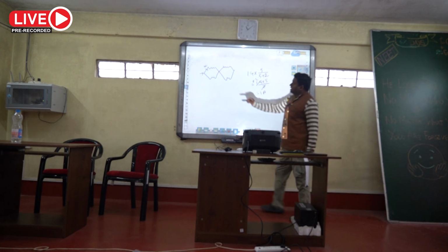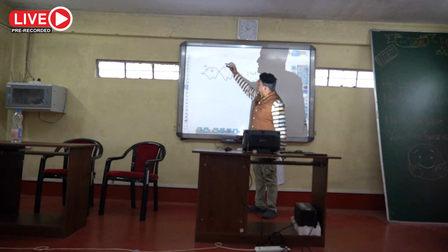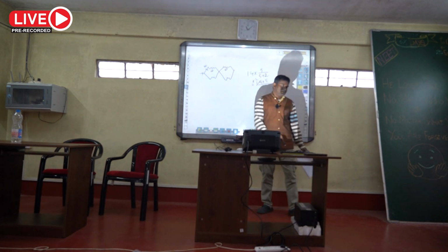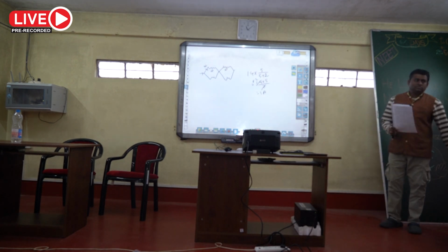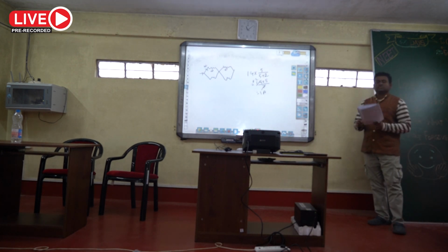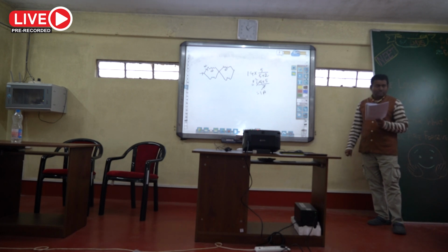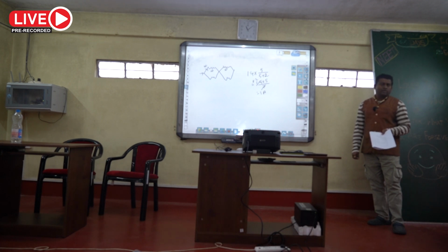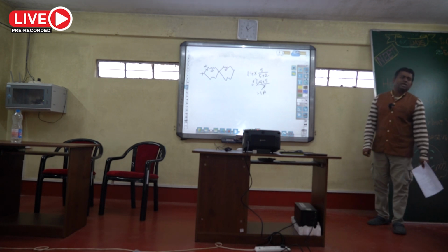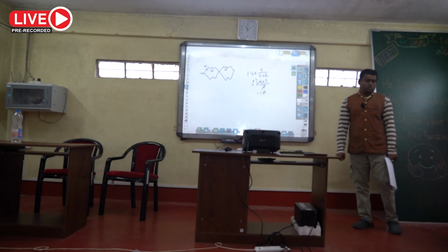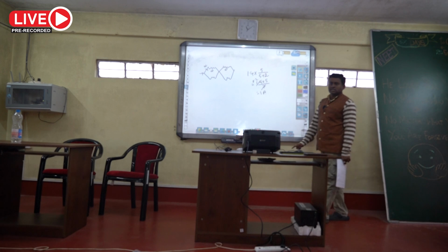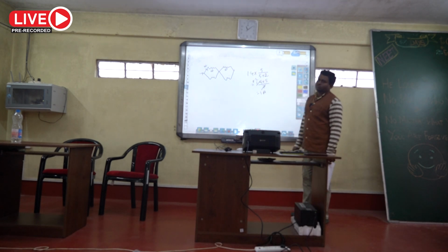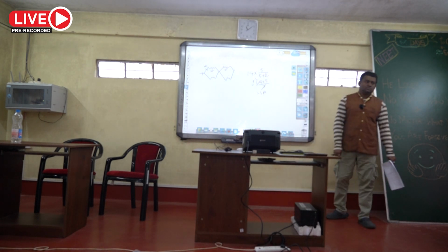Because whatever current is going through this resistor is the same current going through this resistor. So the ratio is 2:5. Through the larger resistor, small current will go, because in the parallel combination I1 R1 equals I2 R2. So through the smaller resistor, larger current will go. So it will be 5 by 5 plus 2, the ratio.